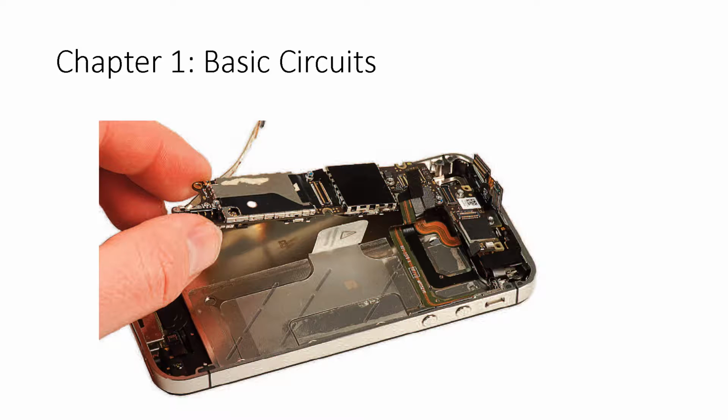Another thing the mechanical engineer has to do is to be able to design the chassis, or this metal piece. Right here it looks like this aluminum was milled out on a milling machine. Milling is usually a pretty cheap process, especially for high batches. And it also gives very, very high tolerances as well, depending on how you do it and what type of computer control you have. So the mechanical engineer has to be able to fit all of these different electronics into the package or into the chassis.